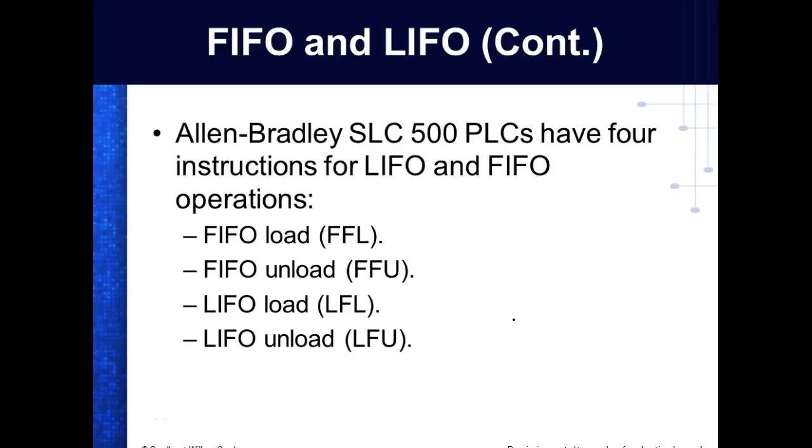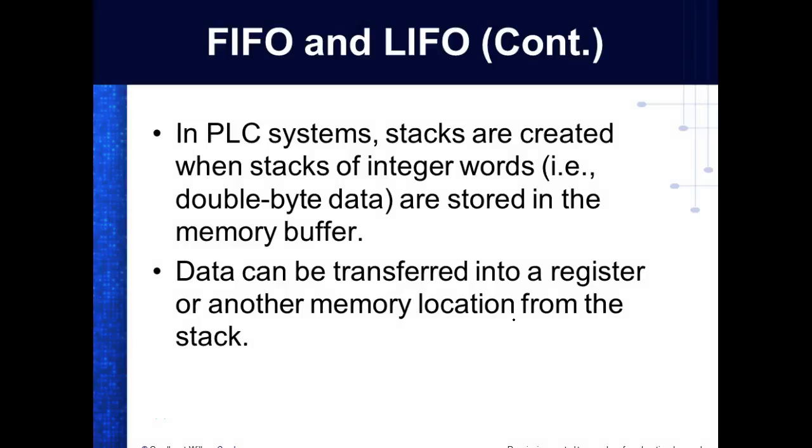Well, let's look at the example in the book. In the PLC, all we have is the stack pointer. It's not like the index register. The index register is fixed. So if you're using index addressing, by George, you're going to be using S2 colon 24. The only thing that's specified about the stack pointer is that it has to be an integer register. So it has to be one of your N7. You set up the stack pointer.